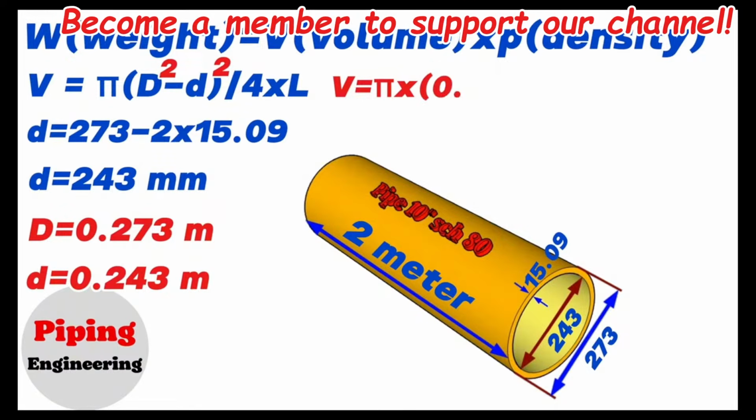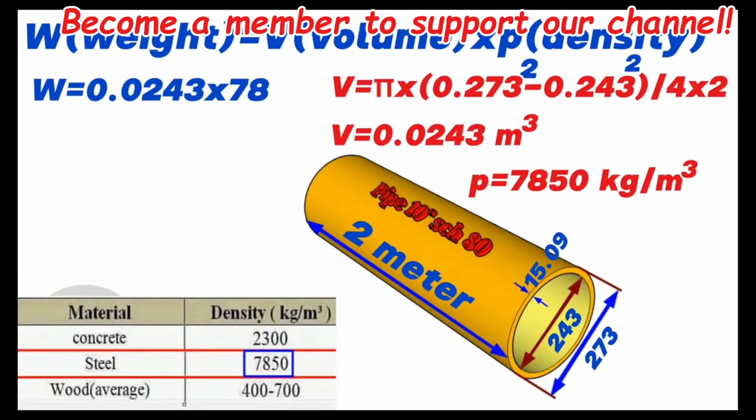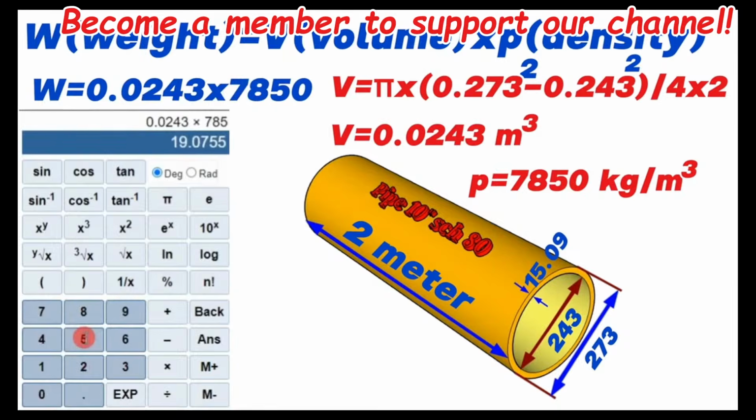Weight equals volume 0.0243 cubic meters multiplied by the density of the material of the pipe, 7,850 kg per cubic meter. Using the calculator, we find that 0.0243 multiplied by 7850 equals 190. So, we calculated and found that the weight of the 10-inch pipe in our example will equal 190 kilograms.